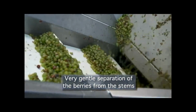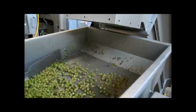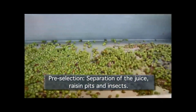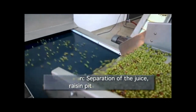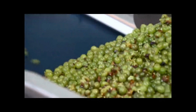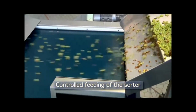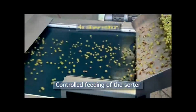In this case, if you look at them, then the grapes that are heavy go through the conveyor belt going up, and then here I've got a vibrating screen to remove maybe any other foreign matter that may be present, insects, pits, and then now you've got a very high speed conveyor belt, which then takes in these grapes. Some of the materials will then fall down because they do not get onto the conveyor belt, and those materials are collected. So this is what they use for controlling the feed. Also operates as a sorter.